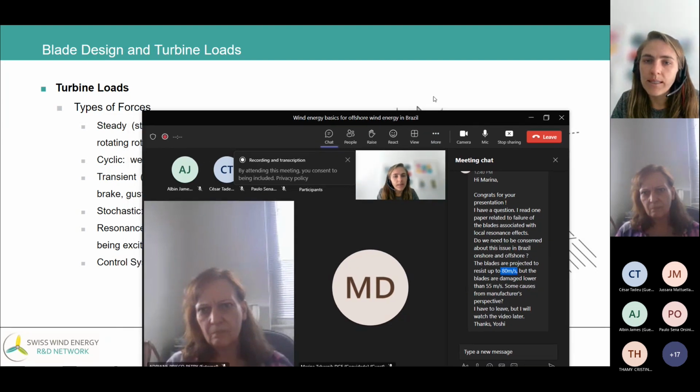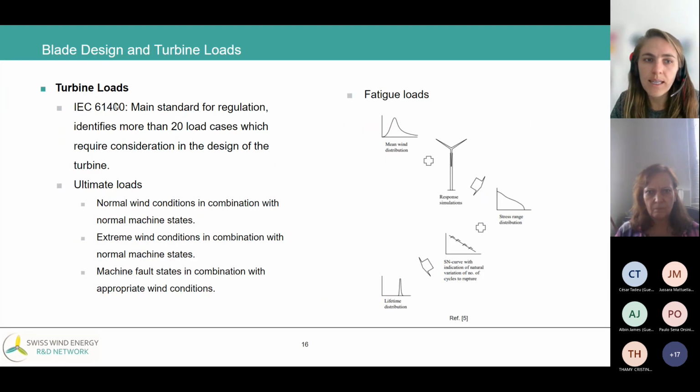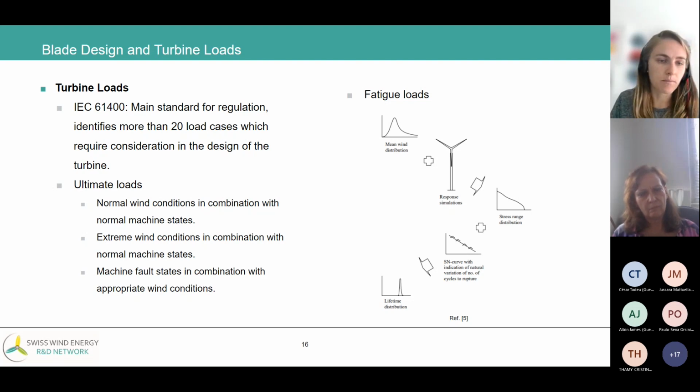Usually, for example, in this IEC standard, we define the wind speeds that we have, for example, extreme gusts in a 50 years scenario. And the values that I have in my mind are around 40, 42, 48 maximum meters per second. And then it's not only the blade, but all the components need to resist these wind speeds, extreme wind speeds.